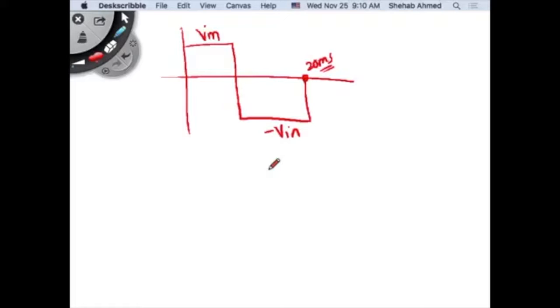That many other stuff will not count, because the power is equal to V times I at a certain frequency times the cosine of the angle between them. If I don't have V's at the rest of the I's frequencies, then it's useless. Then all of these other currents are not helping me deliver real power to the system. But here, it's a square wave voltage.